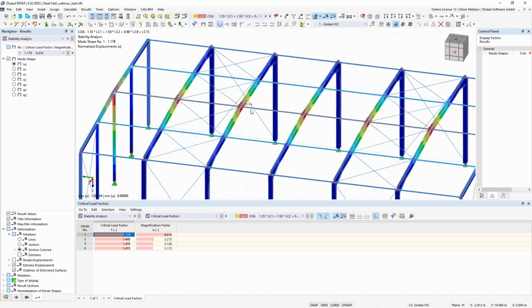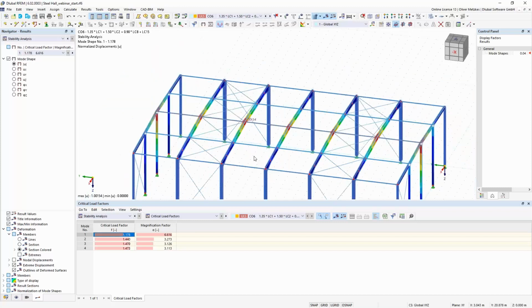So you can see that the stiffness of all the adjoining elements is directly considered, and there's no need to calculate a certain equivalent spring stiffness in this 3D analysis. So you can use the combination of the structural stability add-on and the torsional warping add-on to perform detailed stability analysis on 3D models with member elements. Okay, so I think those were the examples that I wanted to present to you, and the two add-on models. Now I can give back to Andreas.